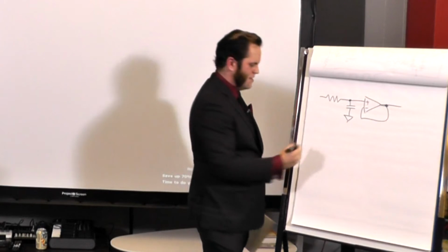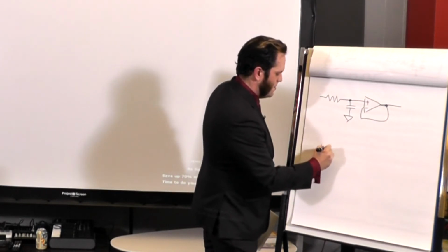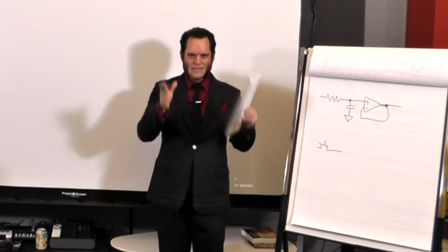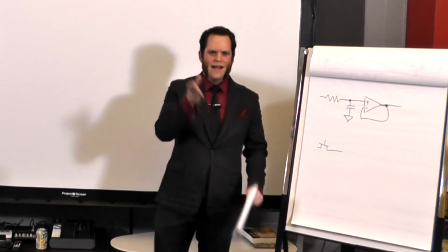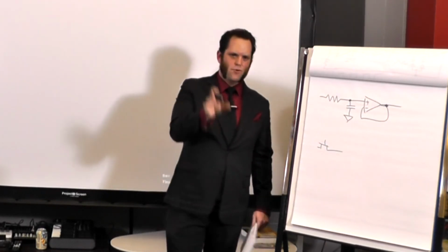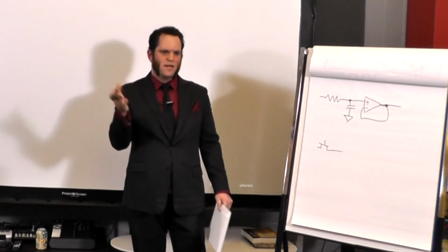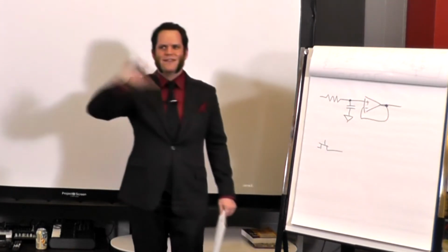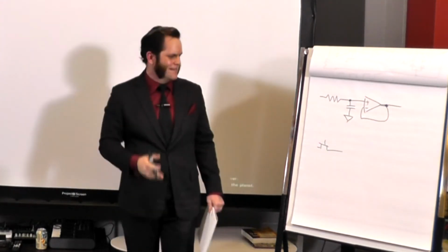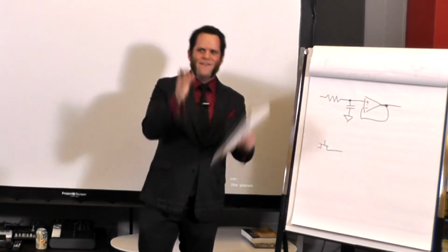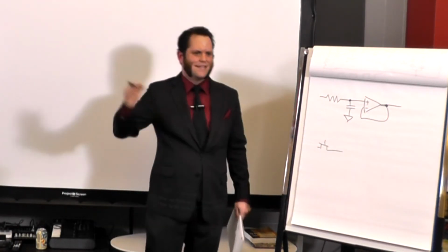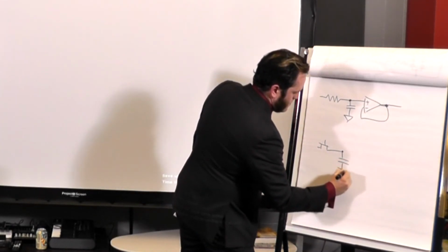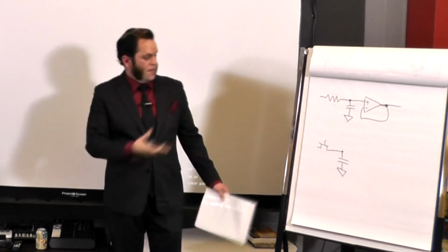Well, we've got a really cool trick that you can do to tweak the resistor. It requires a little bit of messiness, but you can put a JFET there if you want. And you just need to drive that JFET in its linear zone. It has this very narrow band of voltages where it's acting like a resistor as opposed to an on-off switch. And so unlike most modern digital tech, where you're like, we hate that resistor zone and we want nothing to do with it, and we want this FET to be on-off and nothing else, we're now in a world of, we want that FET to be like a resistor that we can control with the voltage because that's neat. So we could do that, right? That's pretty cool. Right, and then do this stuff. So that's one way to go about it.